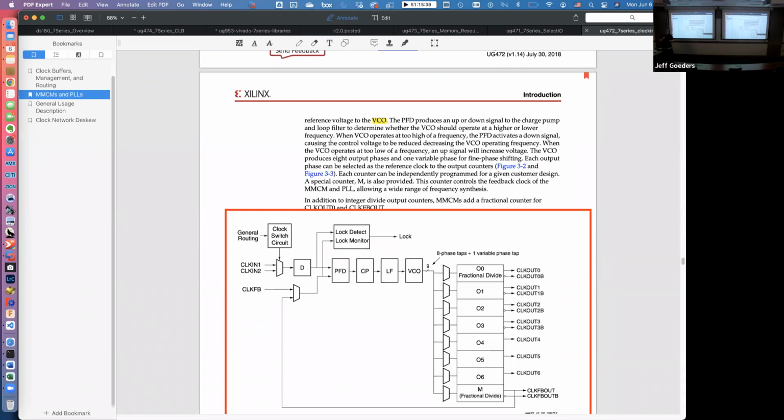Or you just use a second clock, a multi-mode clock manager, MMCM, and you take the 80 from the one, and now you do something to it to get you the 60. So that's more advanced stuff. The deeper you go, there's a lot of stuff. And good designers, people who are doing this commercially and putting it into products, are wringing every bit of performance they can out of the part by understanding more at the level we're talking about today. Okay, that's all I have, and we've gone over by 5.